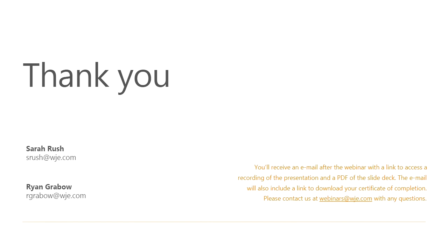Sure. That relates to the last answer a little bit. Having more isometric details, showing what to do at the extents of work areas, maybe thinking through what to do where the shelf angles met the columns or what you wanted to see, might have been a way to help mitigate some of these flashing follies. They could also be addressed in construction too. So those are some things that architects might want to consider focusing on in lieu of a typical two-dimensional detail.